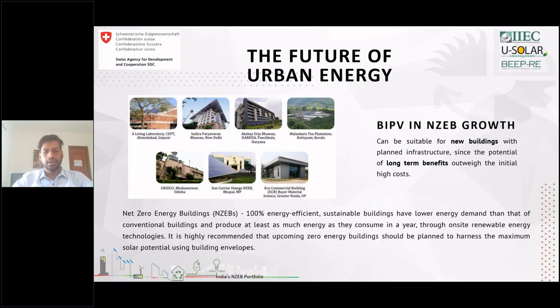For example, in a standard rooftop system, you can orient your modules towards the south with the ideal tilt angle, which gives you the maximum capability to capture 100% of the irradiation available for that location. But with a BIPV structure, because we are integrating these modules into the building itself, and most of the time this integration has a tilt angle of 90 degrees, that is, it's placed vertically, we do lose some of the irradiation.